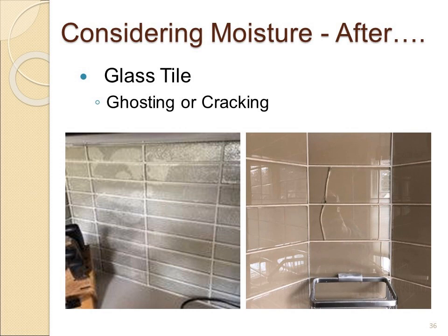And some of the glass tile manufacturers do not recommend using membranes underneath their glass tile for that very reason. The mortar needs a place to escape, otherwise it could affect the appearance of the transparent glass tile.